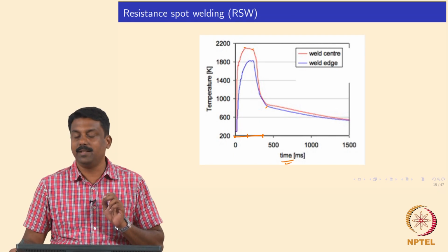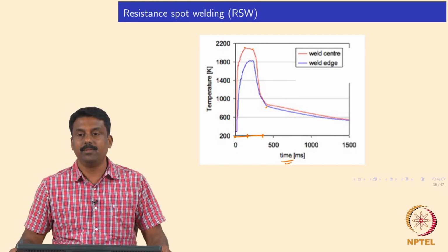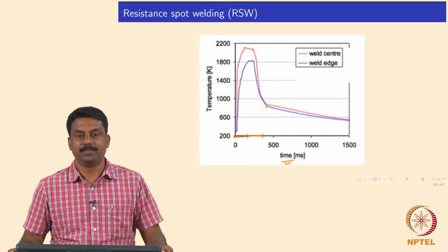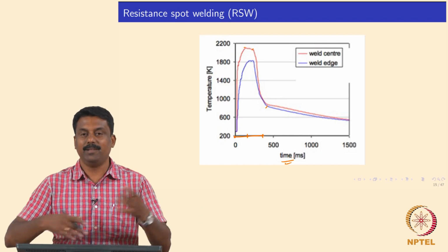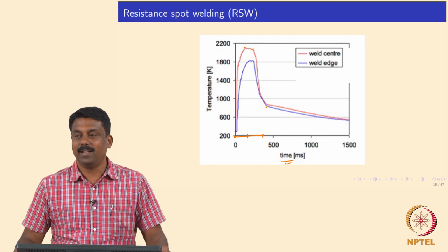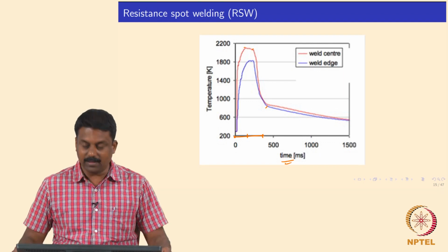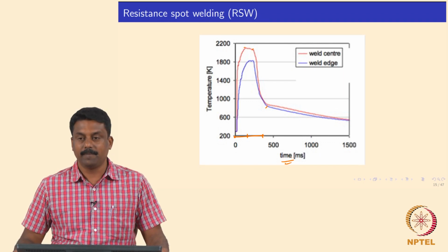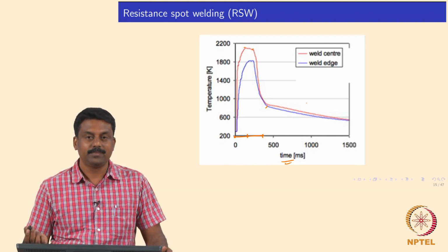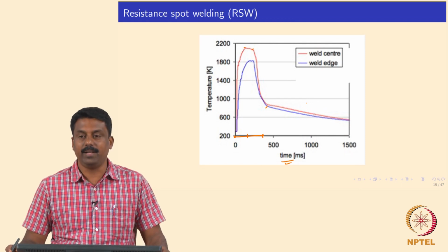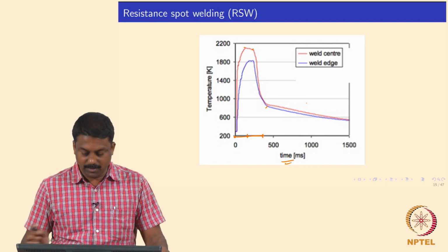So this is what makes this process very attractive for production, where you have to make 5000 welds in 2 minutes. We will have 4 or 5 robots, and they would do all the jobs within 2 minutes. The entire chassis is welded. Because of such fast heating and cooling we use it. And even if you apply a short pulse subsequently, it does not take more than 100 seconds extra. So the entire process can be completed at an extremely rapid pace. Is it clear? Good.